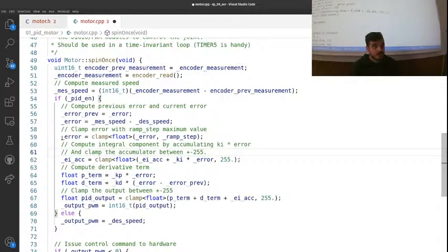To prevent this effect, you limit the maximum integral coefficient accumulated by the PID with a window, by clamping the integral error to a maximum. Yeah, exactly. And we have this anti-windup installed here.